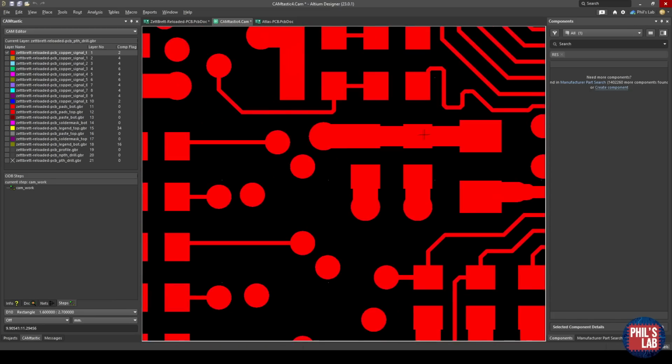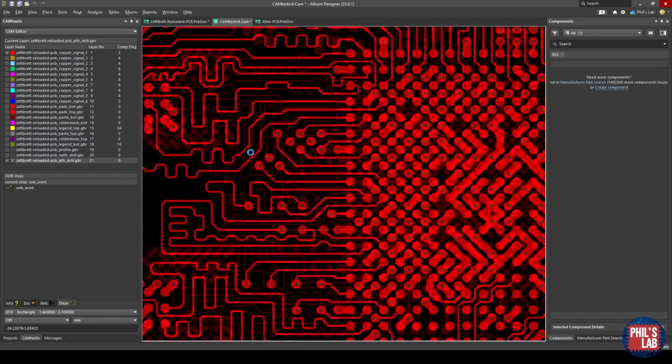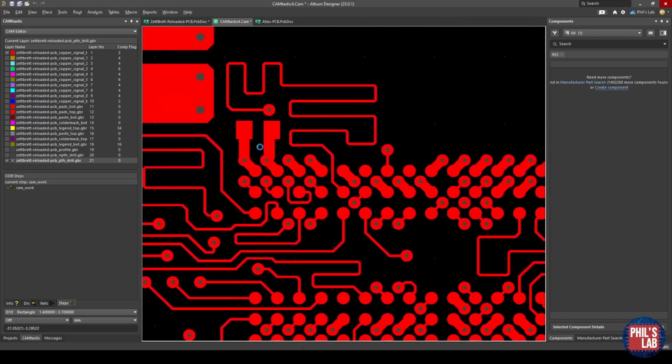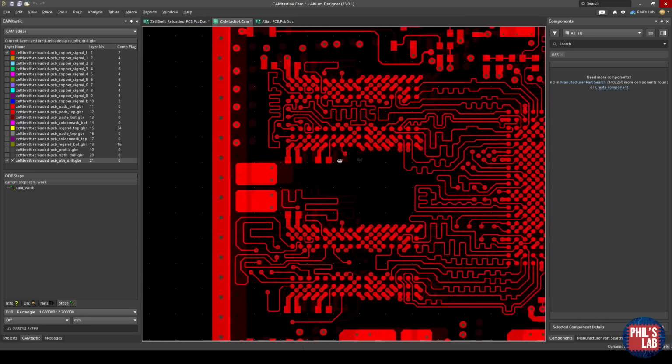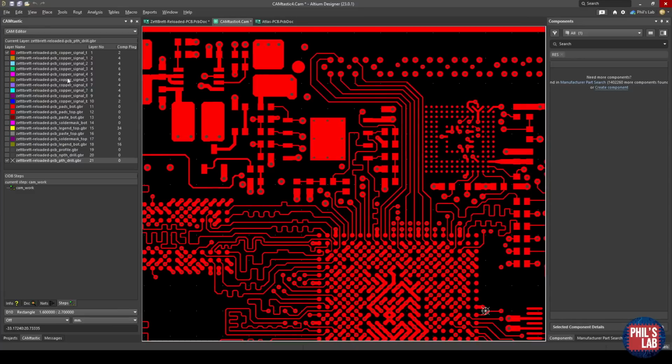Does everything look like it's been plotted correctly? And so on. I could of course also turn on the PCB copper layer and also turn on the drill layer, which allows me to look, okay, have all my drills been plotted properly? And so on. It just lets me spot, rather crudely, some mistakes I might have made or something which I could maybe tidy up a tiny bit.